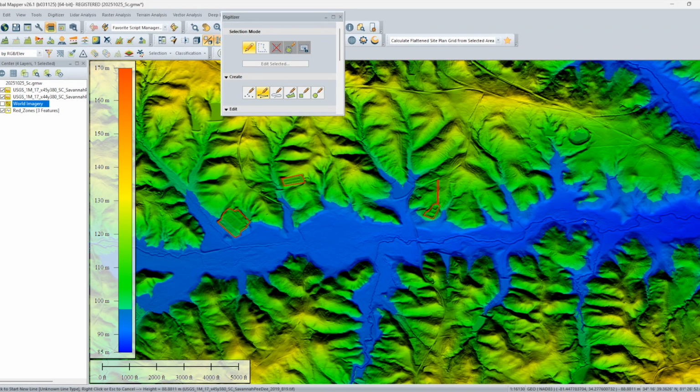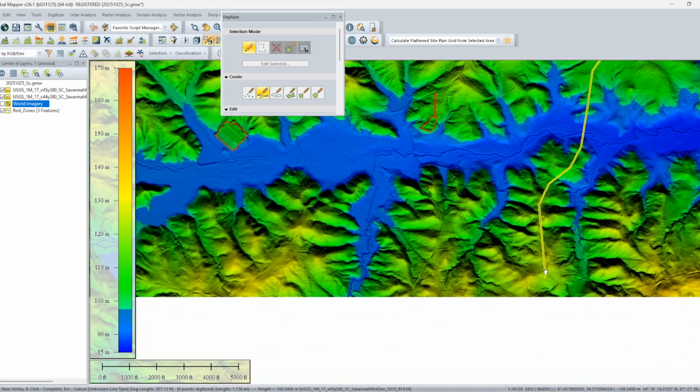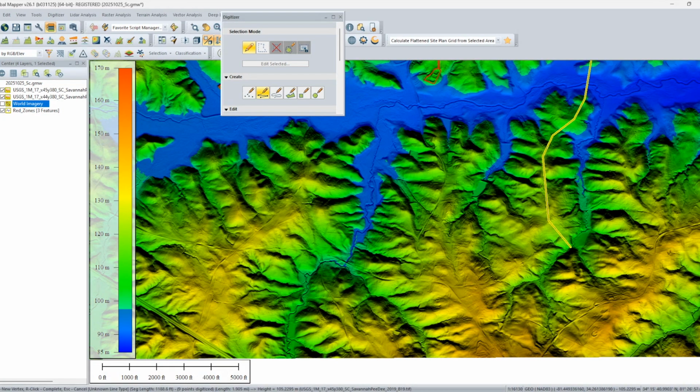Now we're drawing the access road alignment. You almost always need a road over a dam, mainly for two reasons. Firstly, you have to cross the valley somehow. Once you flood it, that shortcut's gone, and you definitely don't want to upset the people stuck on the other side. Second, you need a reliable way for construction flow, a loop that connects to the existing road network so trucks and equipment can move in a circular motion instead of backing up all day. So when I lay out this road, I'm thinking about efficiency and access, a road that serves both the construction phase and the final operation of the dam.